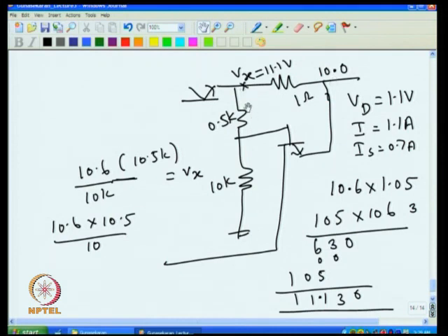So there is no voltage across this under short circuit condition due to this 10 volt. The net result is, under normal working condition you have this transistor reverse biased, and that reverse bias disappears the moment you short circuit. So it limits at much lower current. That is the crux of the issue if you forget about the mathematics behind this, because if you go by the mathematics, it is very difficult to design the circuit.